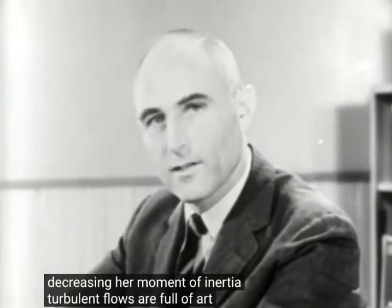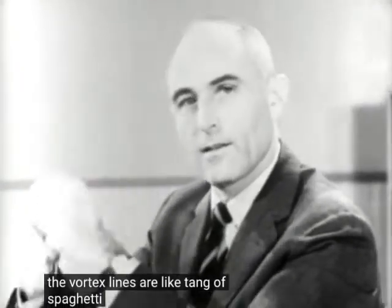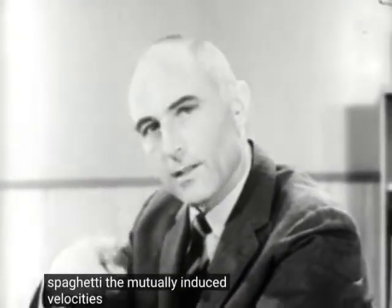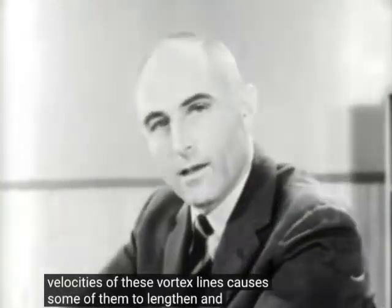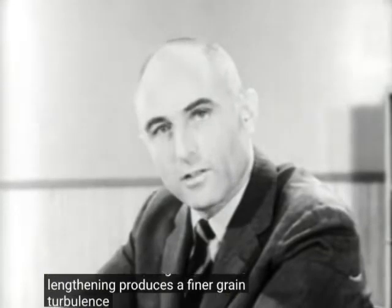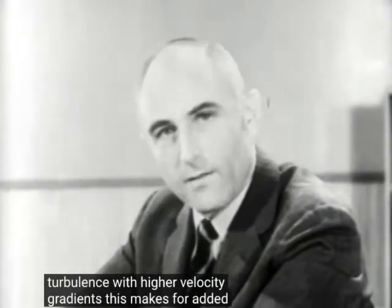Turbulent flows are full of vorticity. The vortex lines are like tangled spaghetti. The mutually induced velocities of these vortex lines cause some of them to lengthen, and this lengthening produces a finer grained turbulence with higher velocity gradients. This makes for added viscous dissipation.